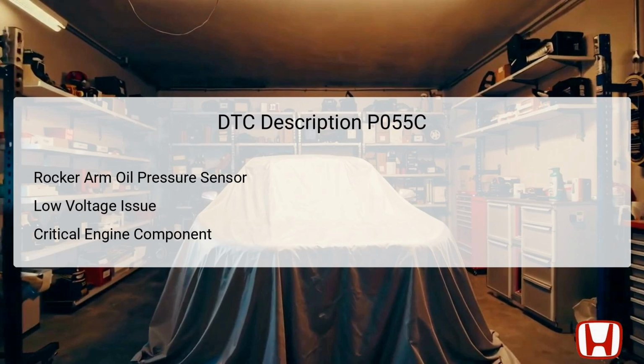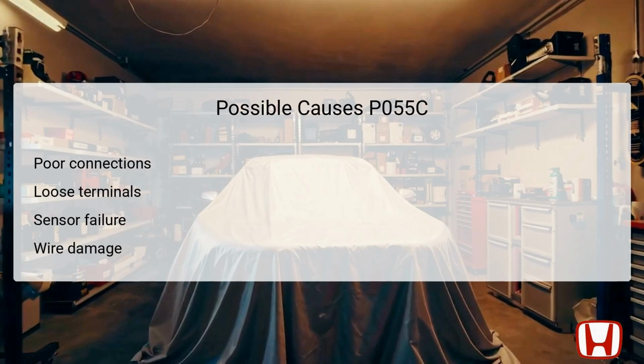This can lead to erratic engine performance or harsh driving conditions. The PCM relies on accurate data from the sensor to manage oil pressure effectively, which impacts engine longevity and responsiveness. Understanding how this component works and where it is located is essential for effective troubleshooting. Several potential causes can lead to the DTC P055C.